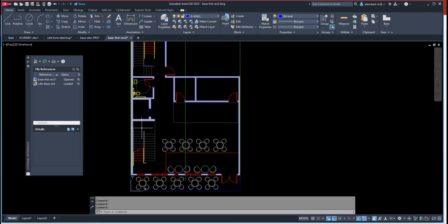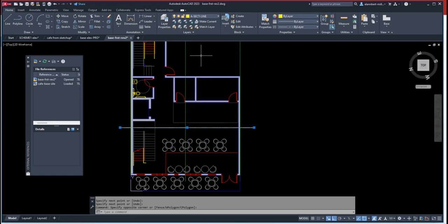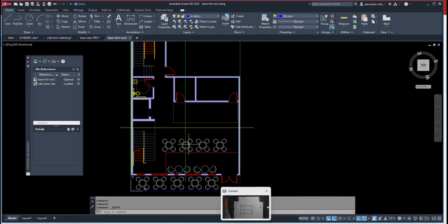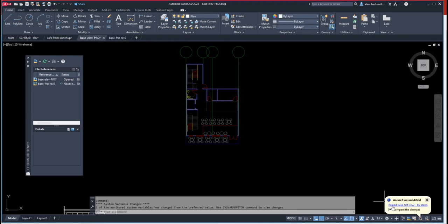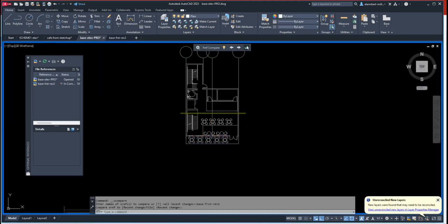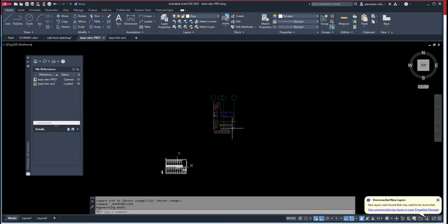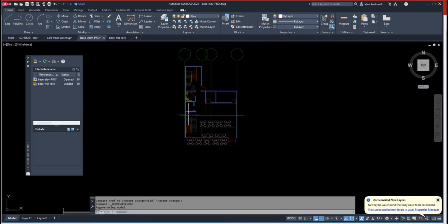Usually stairs are good locations to cut. So we're going to draw a line going through this stair and through this landing, and then go straight like this. Then we assign that to that layer, and there you go. We simply save this, go back to our base elevation, update our XREF, and click OK for yes. The reason why we did this on the base plan is because we need to show this on our base plan when we get to the construction development phase.